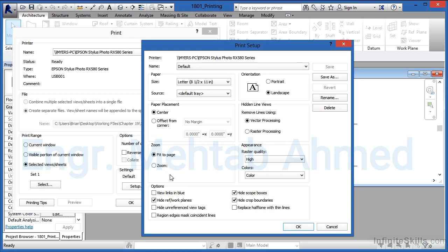As I was doing support on many different Revit issues, I would say that printing to the wrong scale or not getting the print to look exactly right is probably the number one thing that I ran into for beginners. What usually happens is that they don't change fit the page. If it's at fit the page, it will not print to scale. You might get lucky and print the scale, but most likely it'll be a few % off.